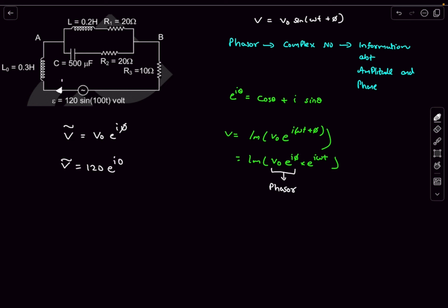Now clearly we want the total current, right? So one of the options actually mentioned it. If it was a DC circuit, what we actually do is figure out the R equivalent, then we do V by R and get the current. And here the ratio of V by I is something that we call the impedance. So impedance is nothing but the ratio of the phasor voltage and the phasor current.